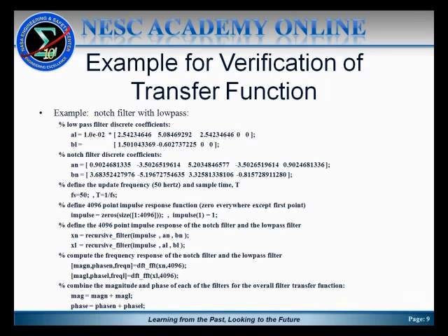And then you individually compute the discrete Fourier transform of the notch impulse response and the low-pass impulse response as shown there using, again, the FFT version of the discrete Fourier transform function. And notice, again, in this implementation, I'm doing them separately. So, we treat the filter as two individual stages, the low-pass stage and the notch stage, and then we'll look at the composite effect of the two combined together.